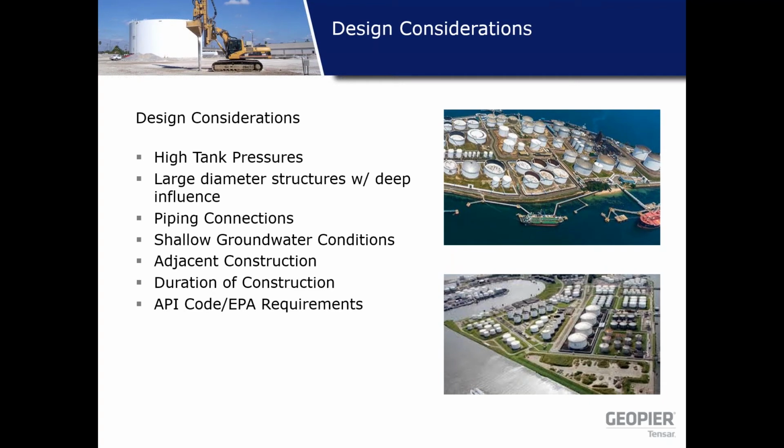What it means is if you have 5,000 psf acting below the tank bottom, about 30 to 40 feet below the tank surface, the pressure delta P is about 4,500 psf. So if you have any soft clays or loose sandy material, even a 5-foot thick layer can cause considerable deformation, which can lead to the settlement of these tank structures.